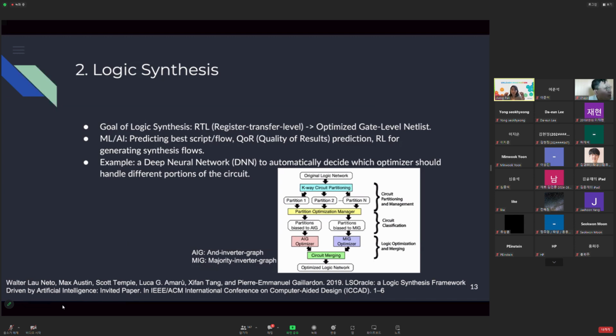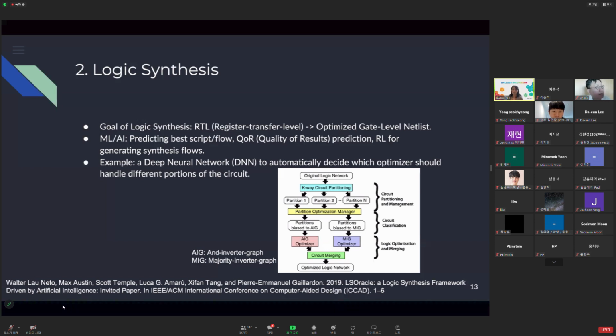And in case of the logic synthesis, this is how we translate the high-level register-transfer-level descriptive language into the netlist. Netlist is the graph that I described earlier. So gate-level netlist. And again, this logic synthesis is done by certain software tools. Like Cadence or our competitor Synopsys, they also sell this kind of tool to automatically do that.